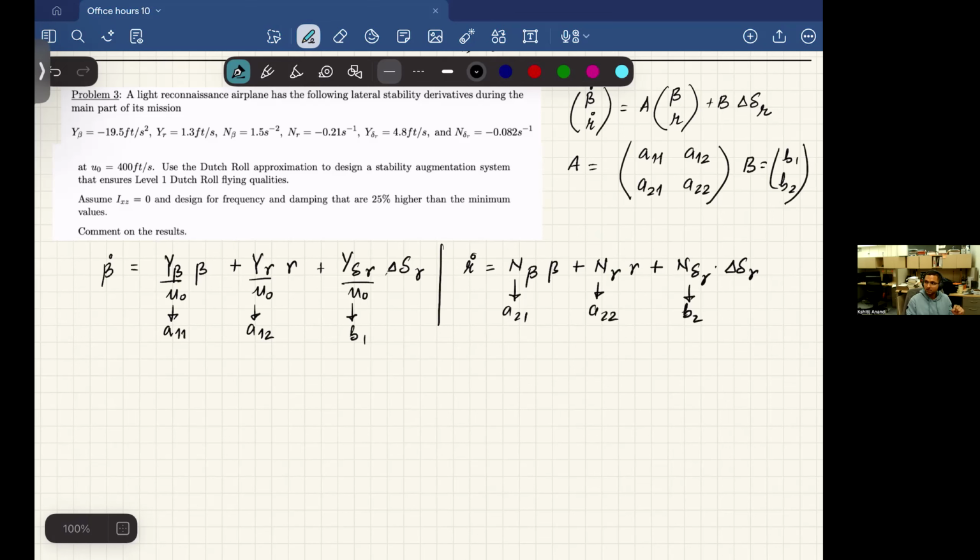The fundamental concept is always looking at which equations of motion I should be looking at, isolating them, and looking at your cheat sheet. We are dealing with Dutch roll, beta dot, r dot. Where are my beta dot, r dot equations? Go ahead and write them down, and be assured that all of those are second order ODEs, so you can always put them in state space format.